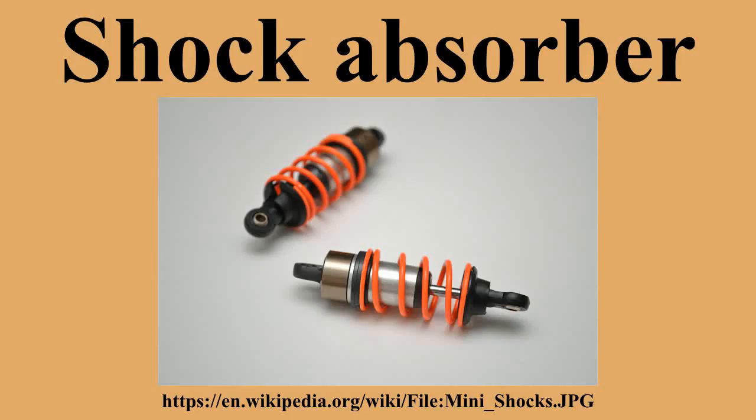Vehicle suspension: in a vehicle, shock absorbers reduce the effect of traveling over rough ground, leading to improved ride quality and vehicle handling. While shock absorbers serve the purpose of limiting excessive suspension movement, their intended sole purpose is to damp spring oscillations. Shock absorbers use valving of oil and gases to absorb excess energy from the springs.